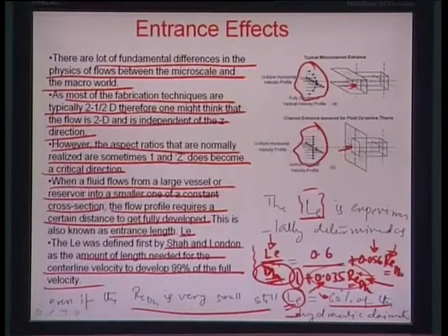So this shows that whenever you want to design a microchannel, you almost have to be careful about selecting the entrance length before the perturbations or structures that you would like to create within the microchannels to cause certain physical phenomena are placed.